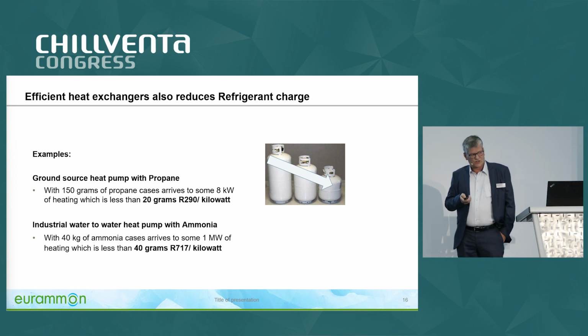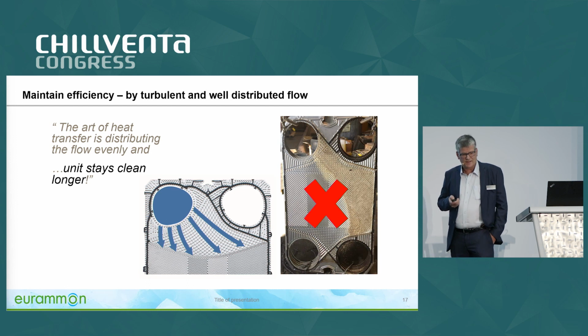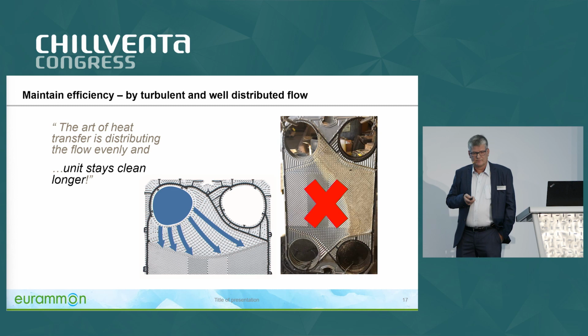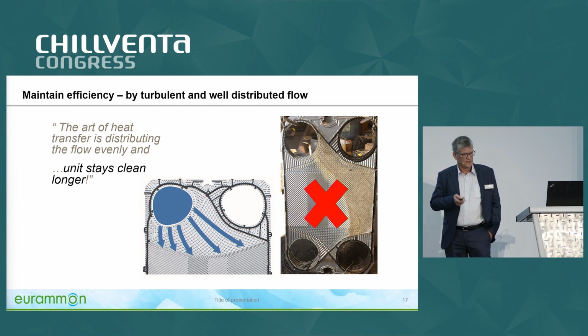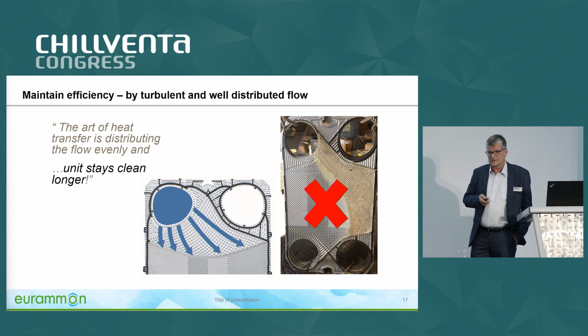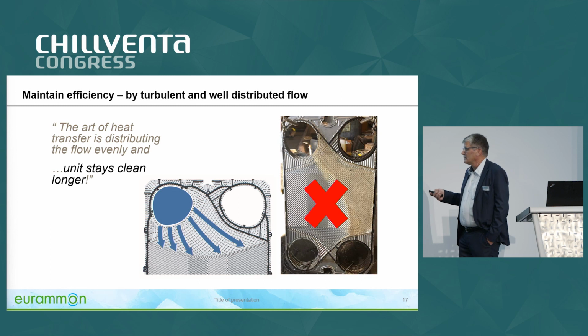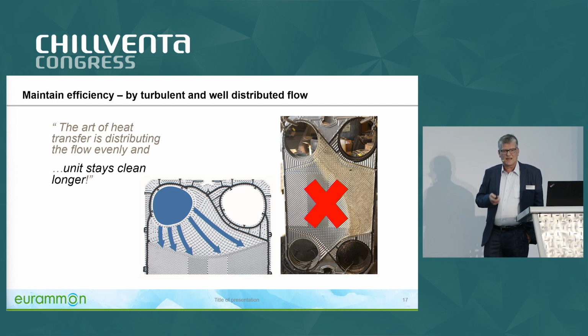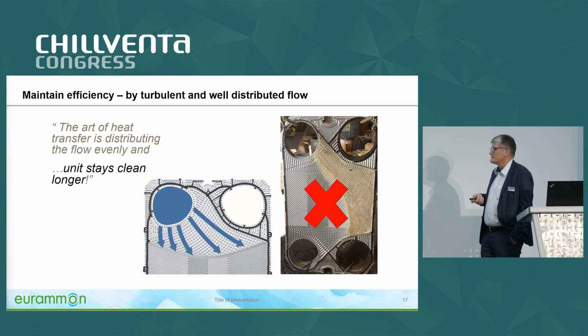Installed, the heat exchangers need also to be maintained, especially if we are talking about a water source that is dirty. It could be a river, it could be industrial waste. It's also important to keep them clean in operation. Also here, on the water side, distribution is very important to have a self-cleaning effect on the plate.